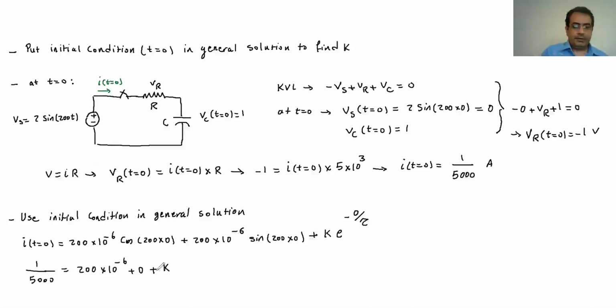So it's going to have the k value. And here it is going to be negative, because we have a negative 1 here. So we have the negative 1 over 5,000 there. And if you do the calculation here, the k comes out as negative 400 times 10 to the negative 6 amp. So that is the k.